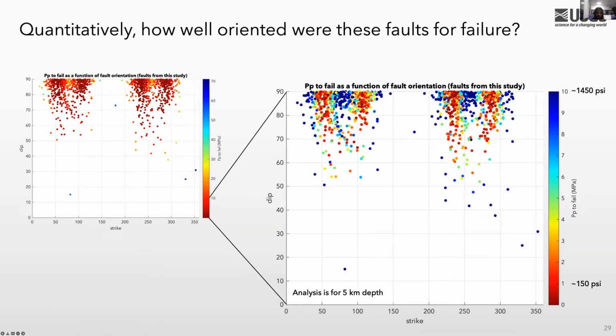And I mentioned earlier that in this case, the depth uncertainty is greater than the horizontal uncertainty in the earthquake event locations, which means that the planes fitted to those events might be steeper than they actually are in reality.